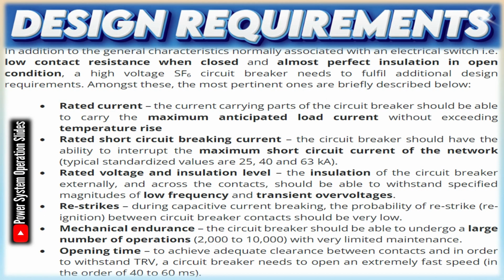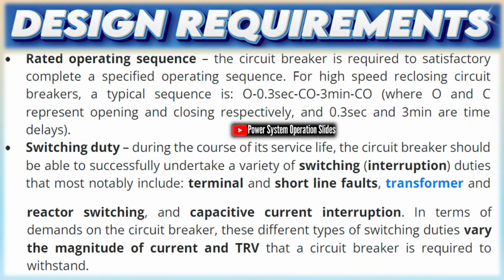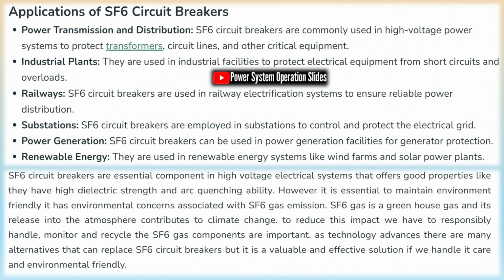For transmission line switching applications, these circuit breakers may be equipped with pre-insertion resistors, PIR, to dampen high magnitudes of switching transient overvoltages. These PIRs, normally 300 to 600 ohms, are connected in parallel with the CB main contacts. They are inserted in the circuit for a specified time interval, 8 to 12 milliseconds, before main breaker contacts are closed. Different configurations of SF6 circuit breaker: the external connecting terminals are fitted with grading rings to ensure that the electric field stresses at the terminal surface do not exceed corona onset.